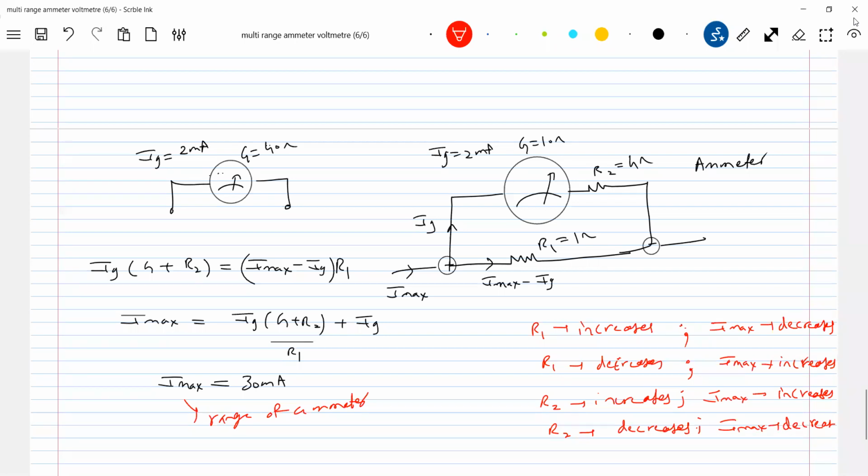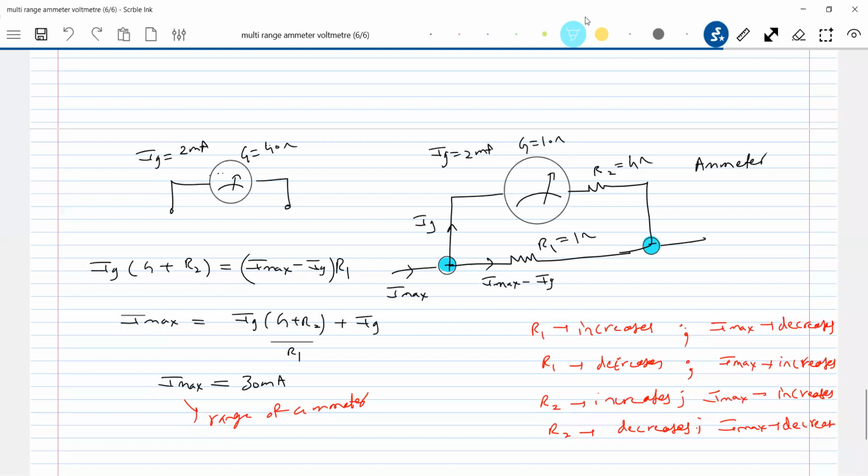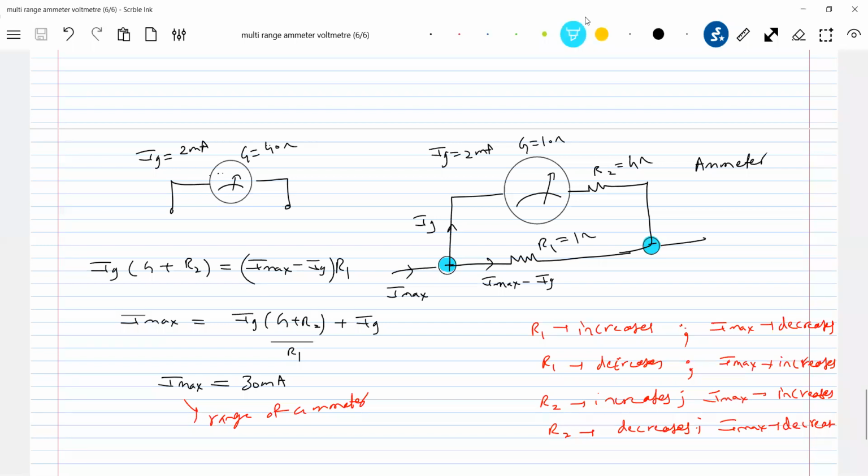Check this condition. Why did you bring this particular setup? What is the problem with the low values of shunt? In the morning we also came across values like 1.01 or 0.00, those orders will come. Manufacturing a shunt of very low resistance, less than 1 ohm, and that too an exact value, is a very big headache. To overcome that, I'll go for this setup.